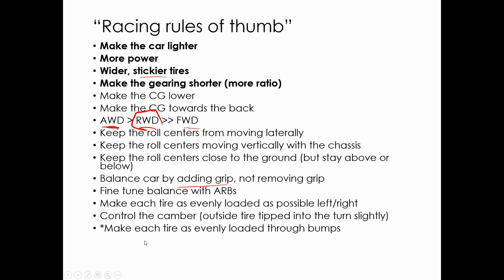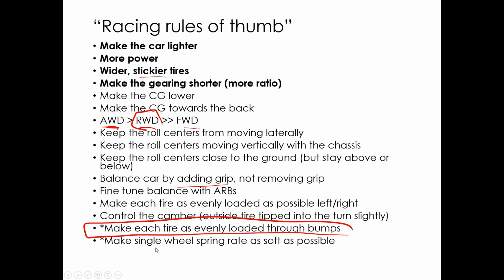Make tires as evenly loaded as possible through bumps. That's shock absorbers. I haven't talked about them at all, and I'm running out of time for this lecture. But with your shock absorbers, what you really want, just because tires are nonlinear, as we talked about, is this: when they're going up and down on bumps and the normal force is changing, you're going to have overall less friction capability than if the force was relatively constant. So you really want your spring and shock absorber to keep your tire normal force as constant as possible. And again, I haven't talked about this at all, so I'm saying this without justifying it.